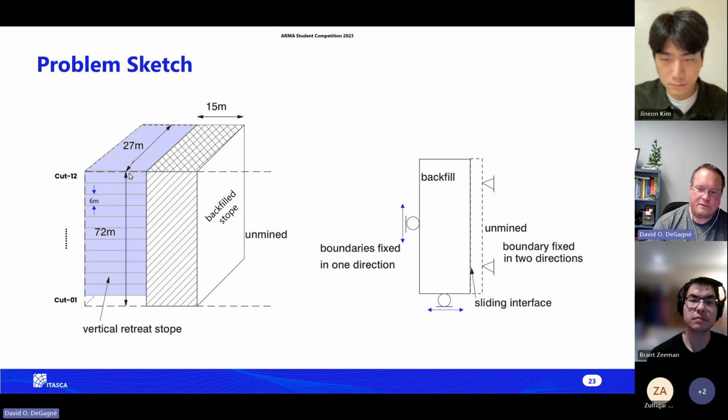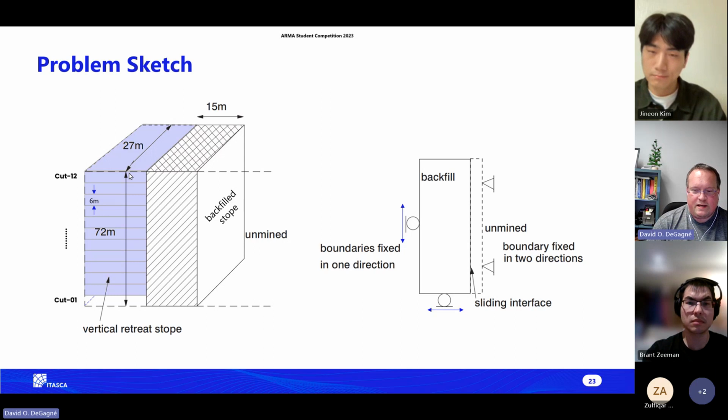You can specify different strain rates, and you might want a different strain rate for granite than for backfill. But if you've ever been to a mining program introduction, trying to induce students to come into the program, it's not unusual for them to maximize the rate and basically detonate the core sample. That's because the load is being applied to the sample in an uncontrolled way and it explodes.